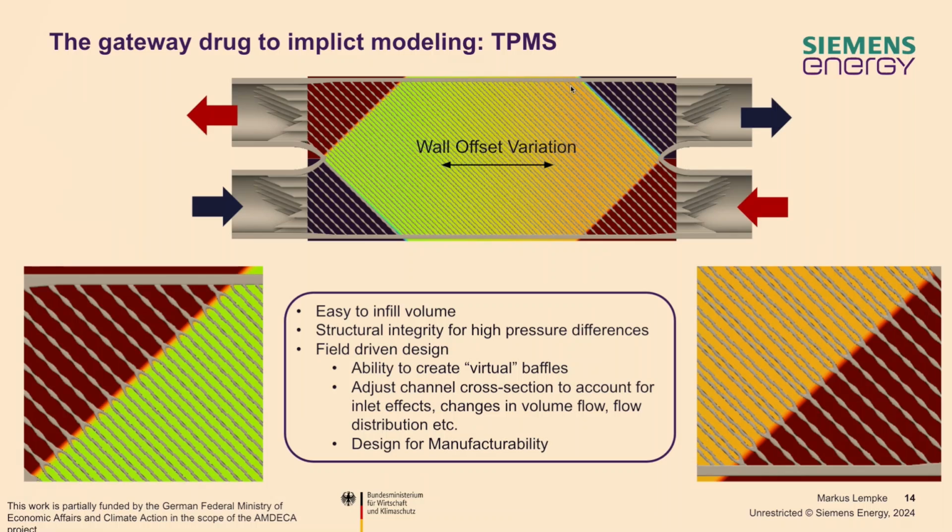That's what you see in those 45 and 35 degree regions here. At the same time, you also see the shade going from green to orange. That's also just changing the bias, and that is important in a heat exchanger, because with temperature the density changes, and therefore the volume flow changes. All this has an impact on your heat transfer, but especially on the pressure loss. If you want maximum heat transfer for minimal pressure loss, this is one of the levers you can work with.